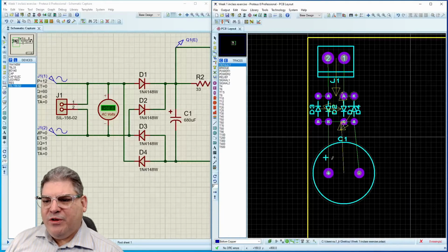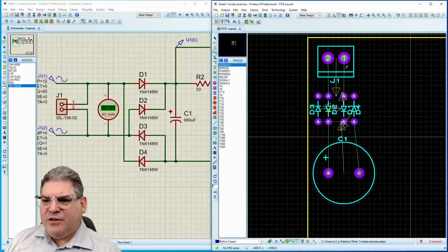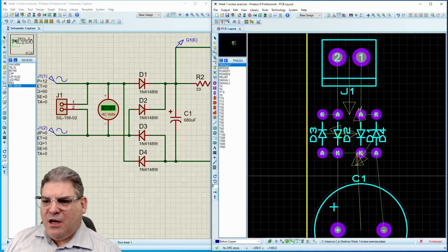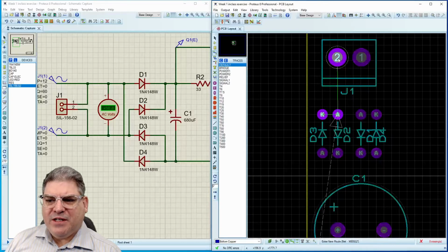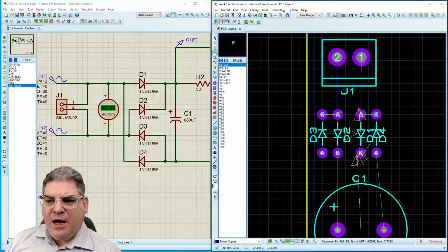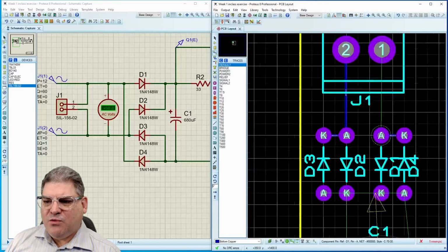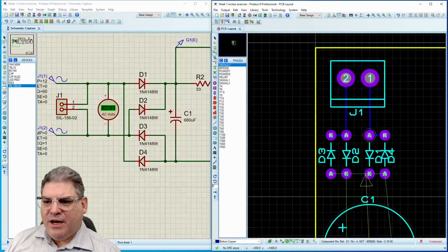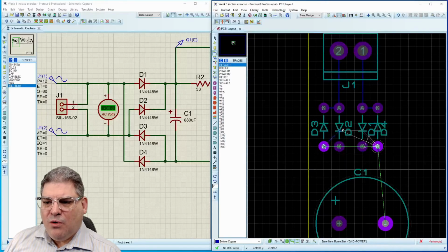And so I'm going to do this portion, but not the rest of it. I want you to do it. Okay. And so when we lay out a trace, we want to start with one of the terminals, and so you have to select a terminal for the beginning and the end. Okay, and then you can do the next one, and the next one. This design is fairly simple, so you should be able to lay this out in such a way that you do not need to use top copper at all.